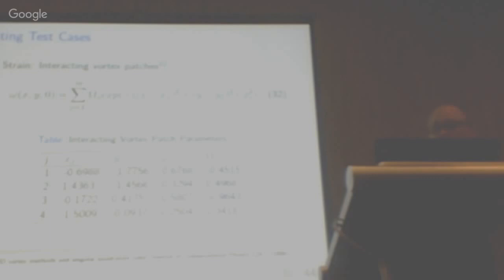The first quantitative test case is one by Strand. In this case, you have 4 interacting vortex patches, varying strengths, varying locations, that all spin about each other. We don't have an analytical solution here, but what we can do is get coarse grids and find as fine a grid as we can tolerate computing, and compare the coarse grids to the fine grid.